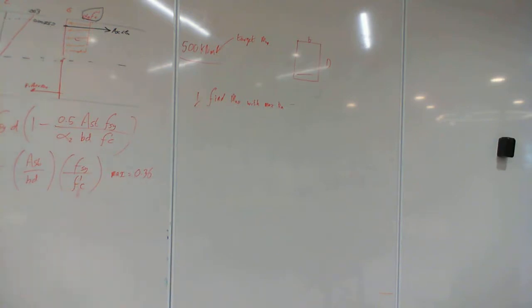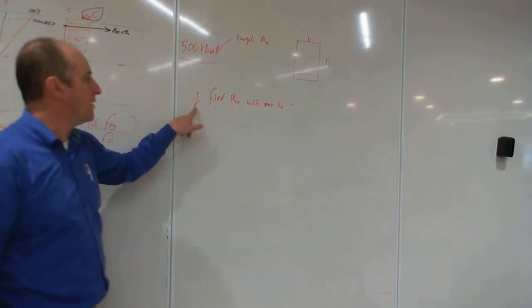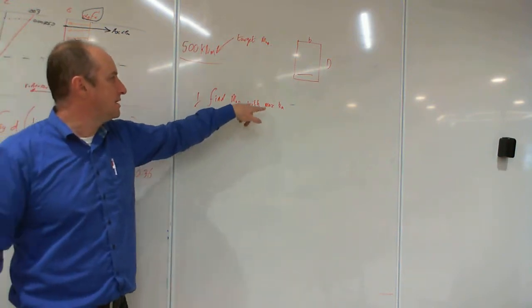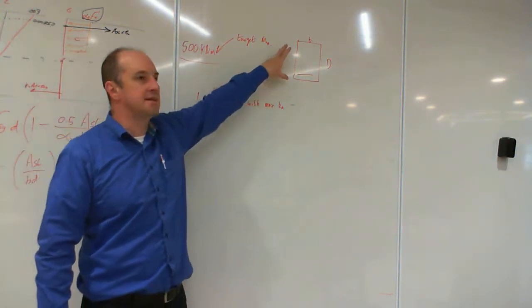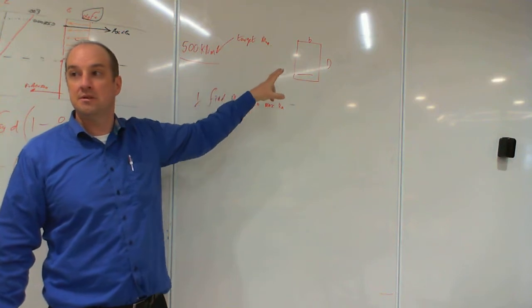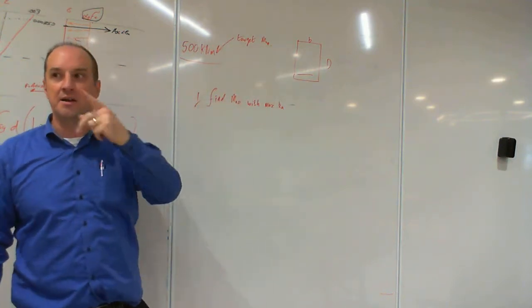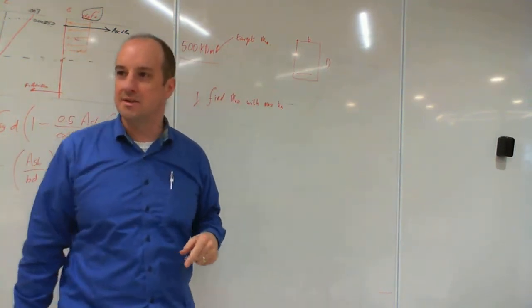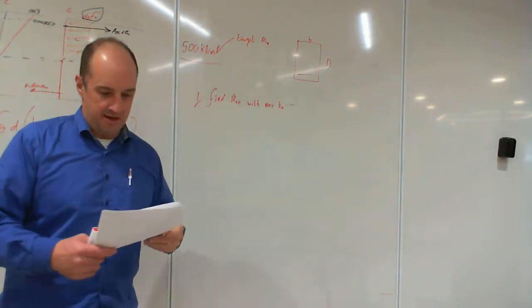Second step then is to put that area of steel into this equation. You know the area of steel, I've just found it. There's the yield, there's the lever arm, all those other things you know, that comes from the concrete strength. You know those dimensions. So you find out the Mu naught with the maximum Ku. That is, in a singly reinforced beam, what's the most that singly reinforced beam could hold? Remember there's phi in there too, don't get lost with that.